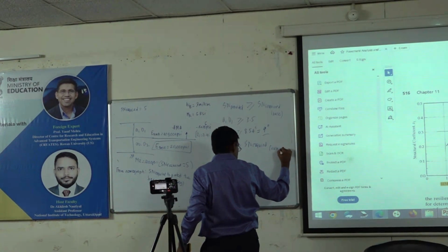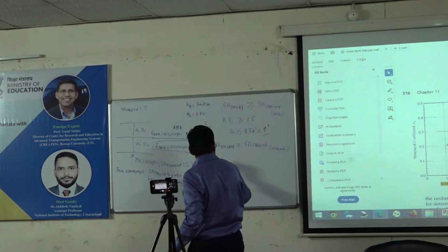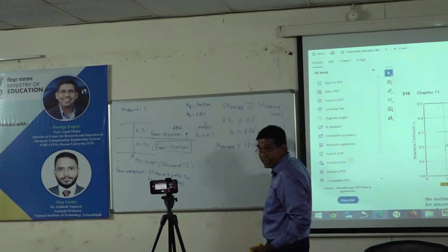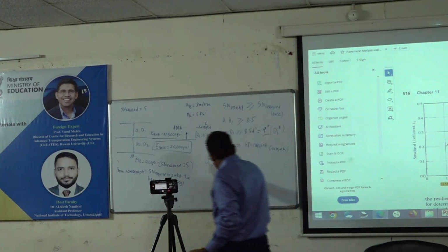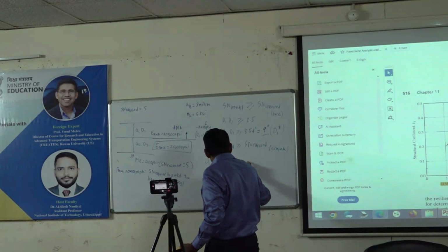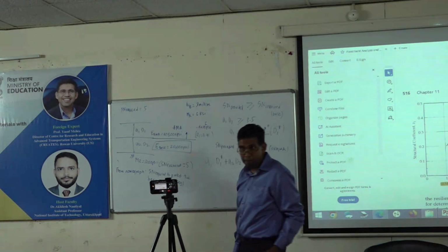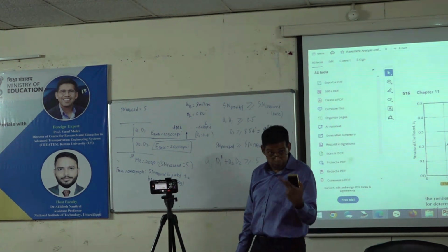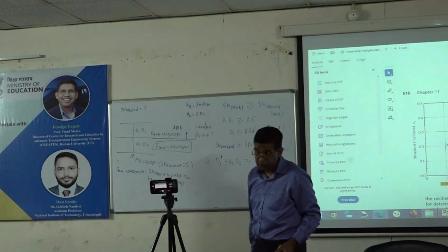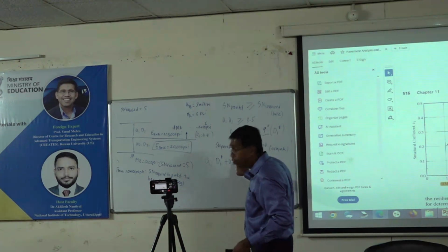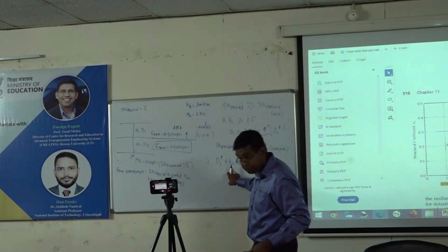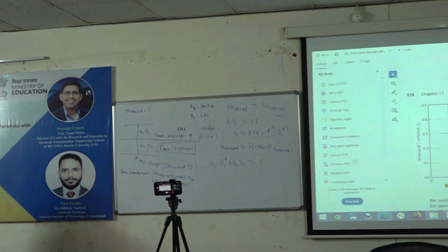Fair enough? Now I have two numbers to protect, A1, and I'll call this one D1 asterisk. This is what I actually provide, 9 inches, right? I've rounded it up. So A1 times D1 asterisk plus A2 D2 should be greater than or equal to 5, yes? Right now I have two layers contributing to 5. I can go multiple layers, right? I'm just showing 1 to 2. I have to find D2, alright? I have to get A2. With me so far? Let's find A2 and then we solve it.